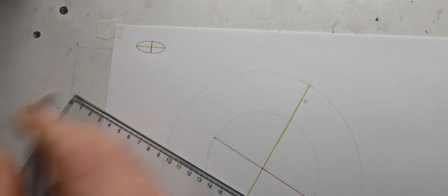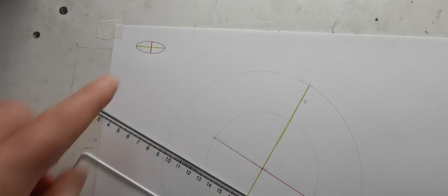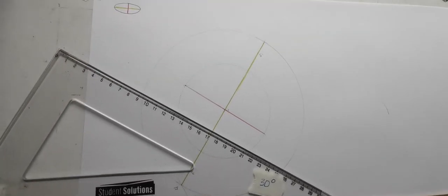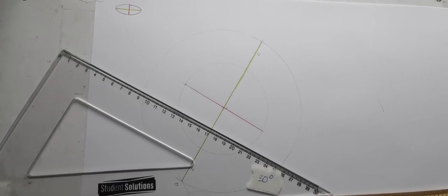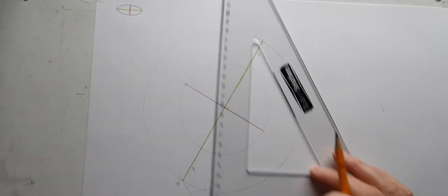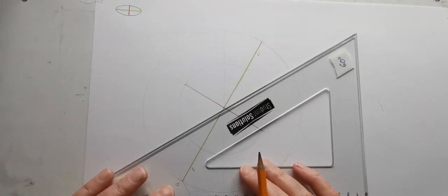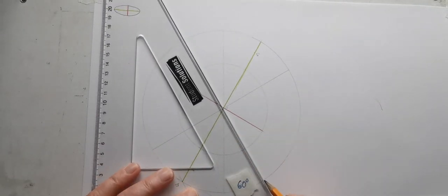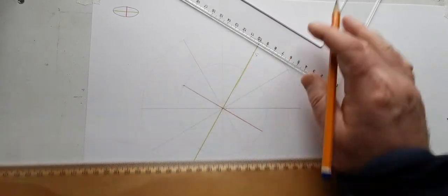So when we're finding our points there, we often think down and across, but really it's parallel to the major and parallel to the minor. So when I'm coming along to do this here now, you must remember there that down and across is basically parallel to the major and parallel to the minor. So I'm going to put on the spokes. Because the axis is at 60, I'm still using all the normal angles. So they're all my normal angles.